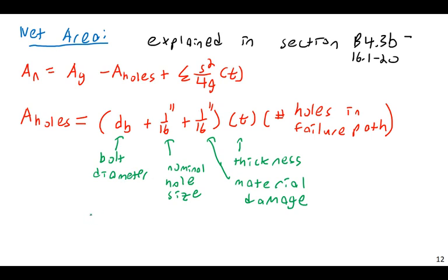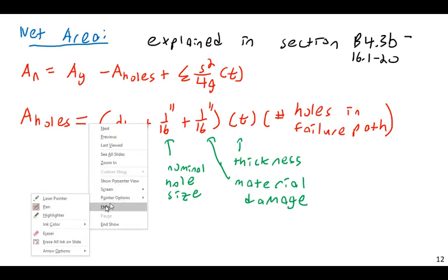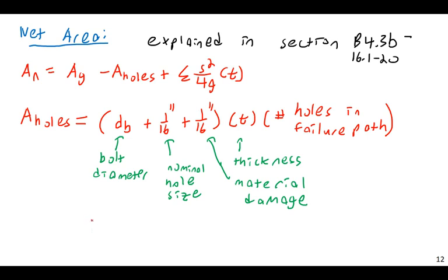But here's the issue though. Drilling, especially through steel, is a rather violent process. You're shearing material planes apart. Essentially here is your actual bolt diameter in the middle, then you have your bolt hole, which is 1/16 inch wider than your bolt.